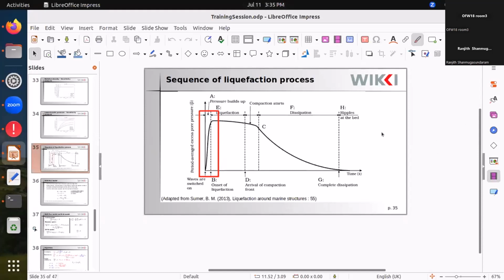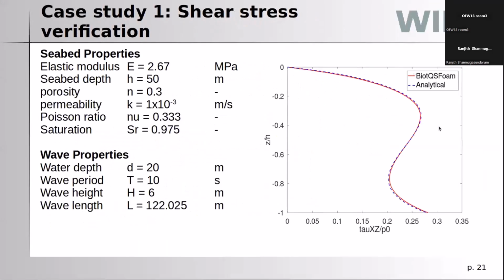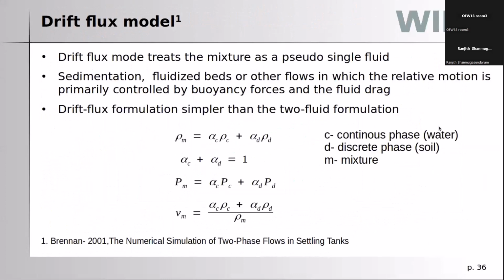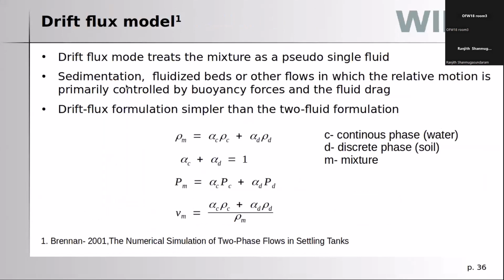So moving further, if you see the liquefaction process, what we have seen till now is only till this part. The pore pressure starts to increase, and then the soil starts to behave like a fluid. In the next steps, we will see how we want to treat this soil after it gets liquefied. For that, we will be using the driftFlux model.